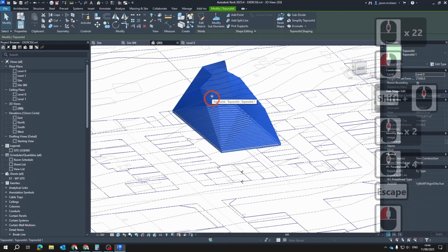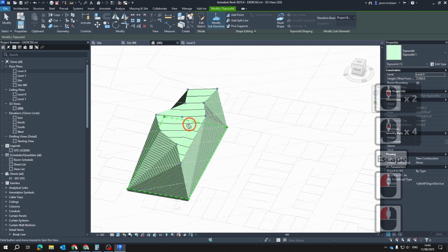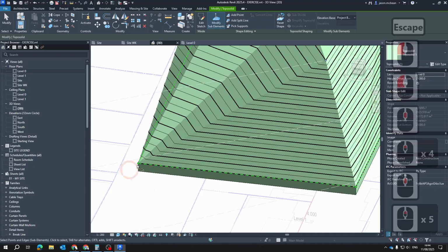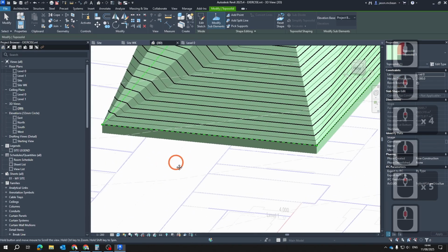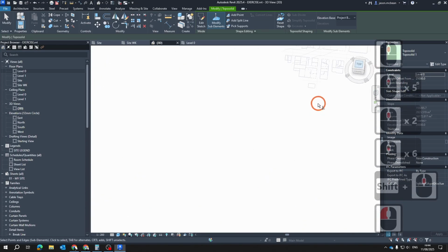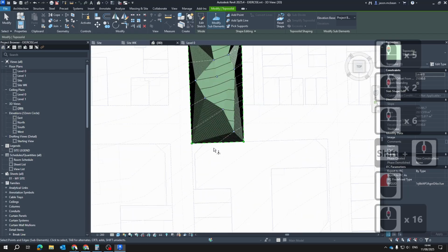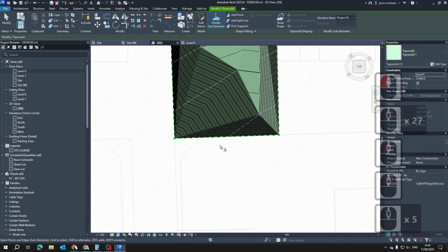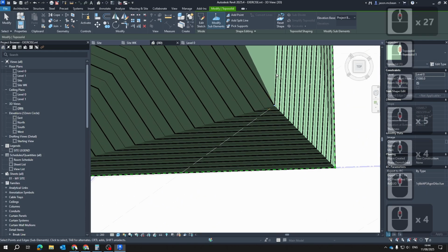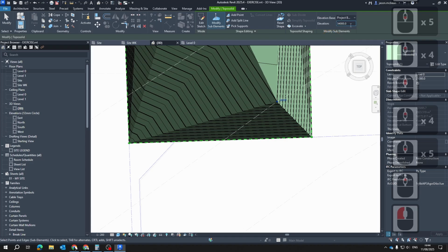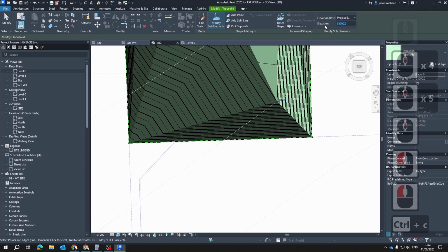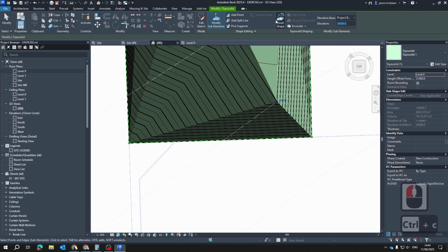So we need to select this, go to edit points. Okay, so go to top view. Now, there was not enough information in this topography, sadly. So we select this point, 34,000, copy that, 34 meters. I'm going to go and add a point.